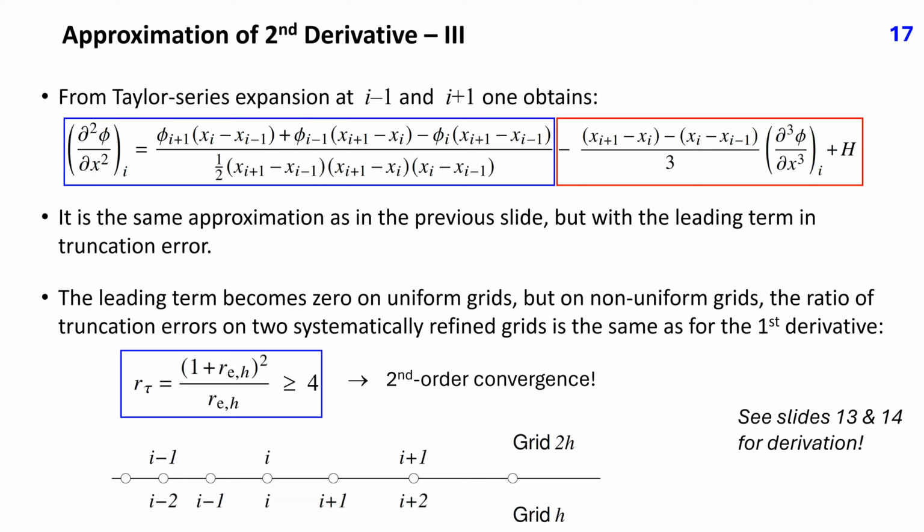For this conclusion to hold, the grid needs to be systematically refined. That is, the new grid points must be inserted between coarse grid nodes such that again a constant expansion factor results, equal to the square root of the expansion factor on the coarse grid, as indicated in this figure.